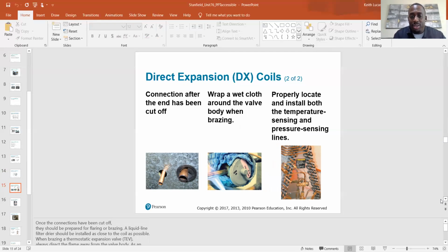So definitely check your coils. If you got something that's a condenser coil or evap coil that's factory charged with nitrogen, it'd be wise to check it at the supply shop if you can before you even go back to the job site. Just push that Schrader valve in and make sure you got pressure in there.